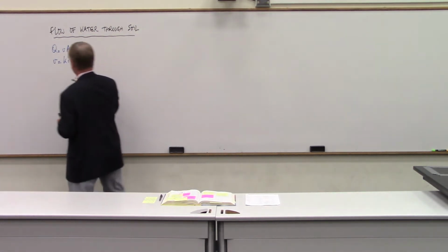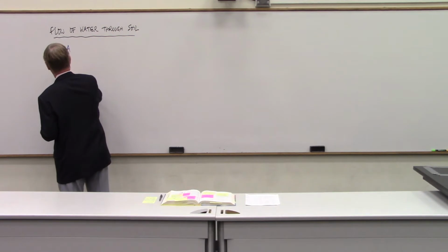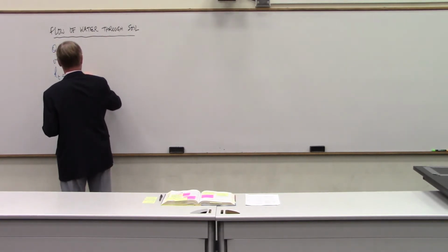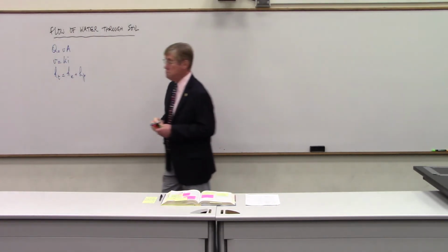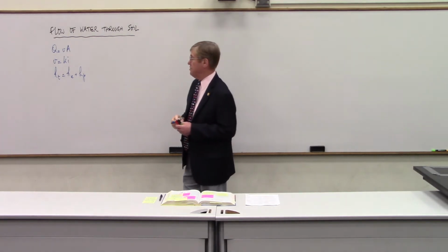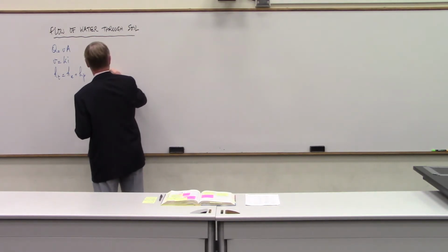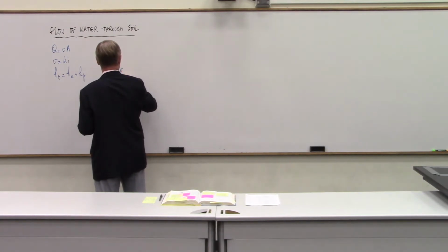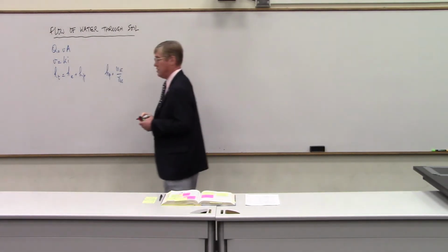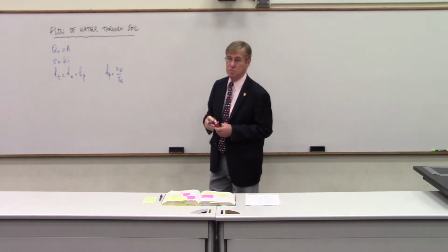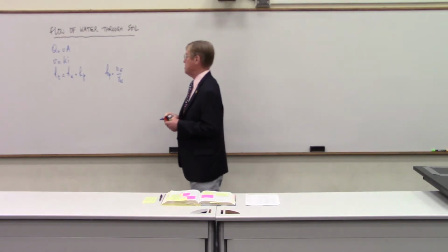We also have another couple of equations that are important. Total head equals elevation head plus pressure head. Elevation head is just how high the point you consider is, and then HP, the pressure head, is UW divided by gamma W. UW being the water pressure or water stress.